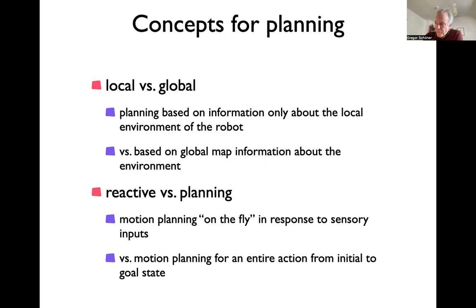While motion planning, in a stricter sense, that's not reactive, would be planning the entire trajectory or path. Trajectory really means that you're also planning the time course, and path would be just a spatial course, and you can run through it at any desired speed. And there are a lot of trajectory planning approaches that are really doing planning, and for instance, some of them actually simulate different possible solutions beforehand, sort of try it out and then search through the space of possible solutions to find one that globally is good, that reaches the goal, and so on. So that's also a somewhat different category of planners.